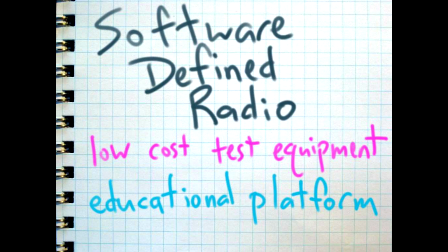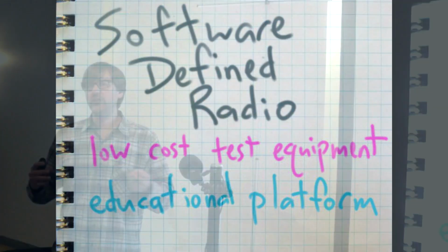So like, today I've helped you learn about components and how you piece things together and how you make your circuit board. But what about the architectural layer? How do you decide when you want to use a mixer? How do you decide when you want to use a filter? All these different sorts of things, like my structure of switches and amplifiers and filters that I had in Yardstick 1. How did I come up with that solution? Well, the way that I came up with that solution was based on my experience with software-defined radio, doing things in software that now I'm doing in hardware. So use SDR as a way to learn about this stuff.